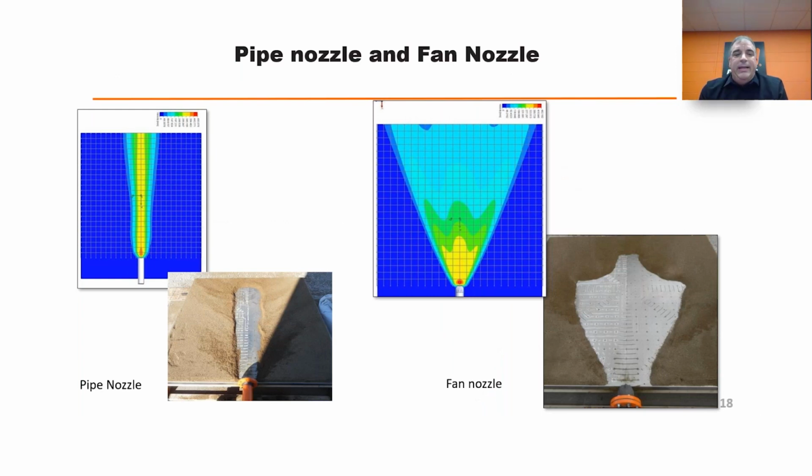There are basically two different types that are used in essence. One is a pipe nozzle, which can be different materials, obviously, but it's basically a pipe. If we're a 4-inch cannon, you're using a 4-inch pipe, and the pipe nozzle gives you the most performance because there aren't changes in direction. You aren't causing turbulence in that blast. So the most force output you will get will be from a pipe.